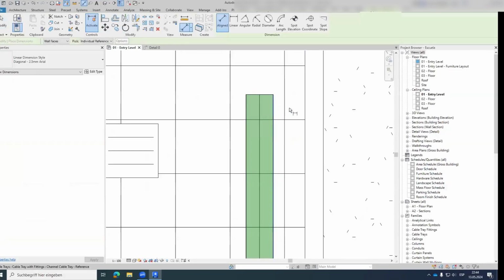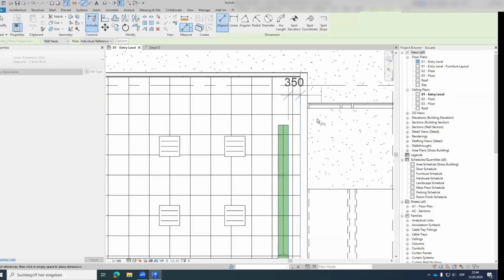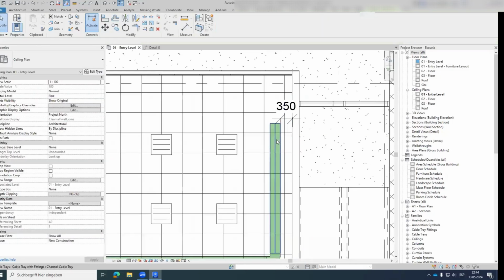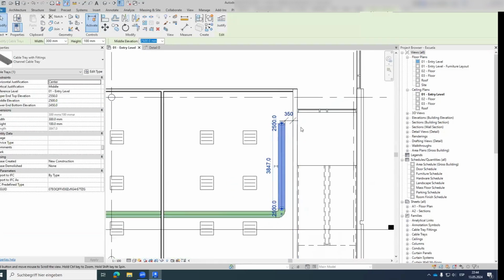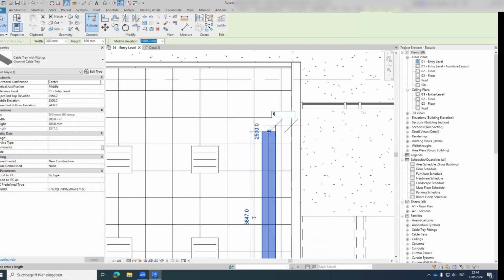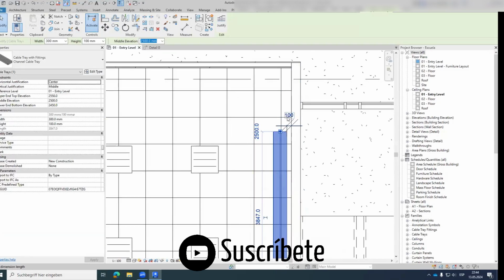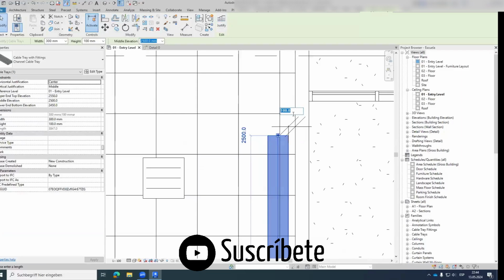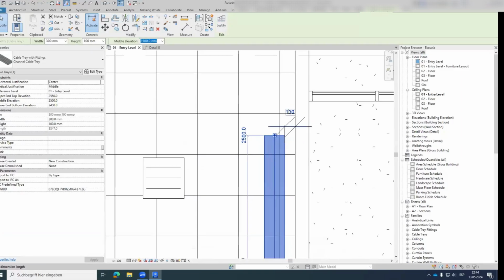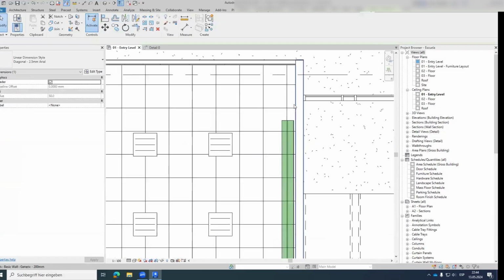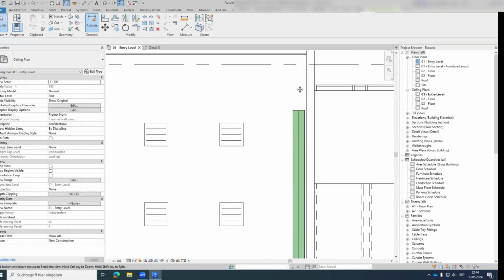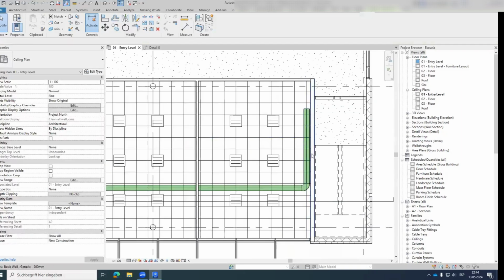This, I need to repeat, depends on the project, depending on how much space and margin we have, but ideally, from the wall, it should be about again 10 centimeters. Others, if you have more space, maybe 15 centimeters. Now, in very tight cases, I have also seen that 5 centimeters is enough from the wall. This also depends on the calculations and the number of cables going into the tray and what other systems or installations are sharing the channel or the room or the space, wherever.